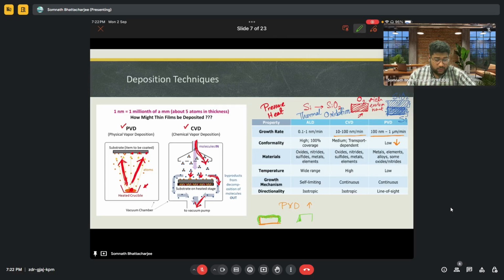There won't be spaces with a conformal coating. In physical vapor deposition, as it's very fast, there are spaces left and there can be errors in the conformation. If the structure is like a square, the structure may look different afterwards. In some places the deposition is higher, and in some places it is a bit lower.